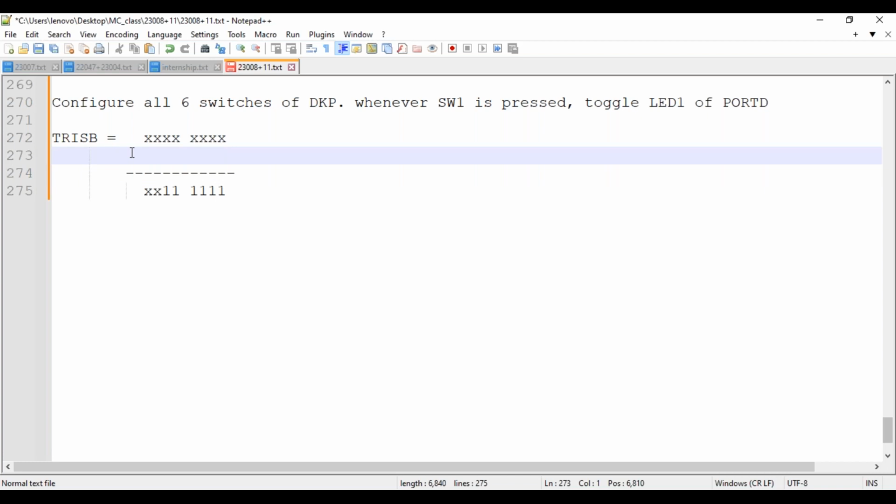I have to set the bits of a particular variable. So how do you think I'm supposed to do it? Which operation? It is setting the bit. Yes, I have to make use of OR. And OR it with what? So we can use the bitwise operators to set and reset bits.